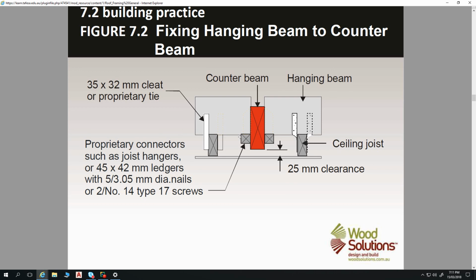Where we do specify fixings, though, is when it comes to bracing. So if you're going to be specifying bracing or tie downs, you'll specify this bracing has 3 2.8 diameter nails at each end, or it has 4, or it has 5, because that gives you different kilonewtons of restraint. Typically when specifying tie downs, a galv strap with 4 nails, let's say, for example, has 2.6 kilonewtons of restraint, whereas when it has only 3 nails, it has a lesser kilonewtons of restraint.